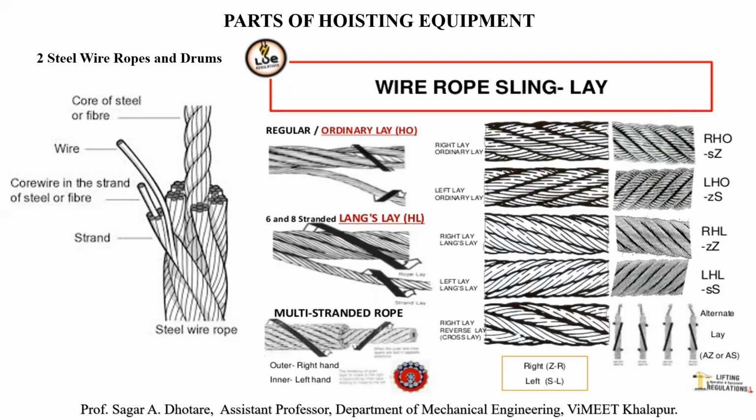However, the wire core reduces the flexibility of the rope, in view of which fiber cores are ordinarily used. Only when the ropes are subjected to high compression, for example when they are wound on the drum in several layers, at that time we can use asbestos as a core material.